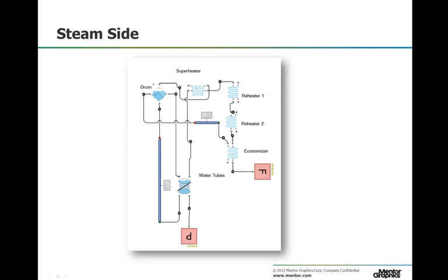This diagram shows the complete liquid system and flue gas system of the furnace. If we look beginning at the drum, we can see the liquid circuit where the water flows downward from the drum through the downcomer pipe into the liquid side of the water tube boiler component and then back into the drum. This is the natural circulation section of the model. If we then look from the pressure source through the water tube boiler up through the superheater and through the individual reheaters, we see the flue gas flow for the furnace.